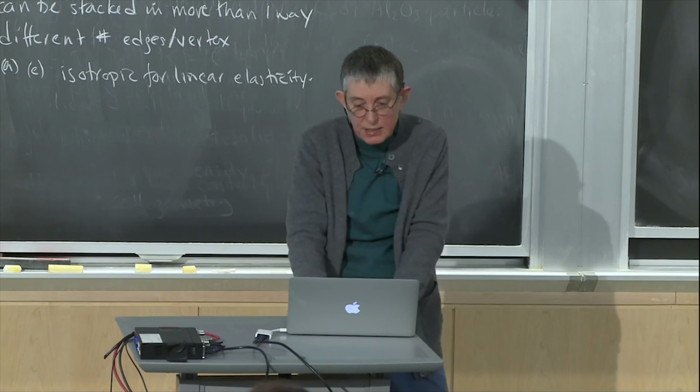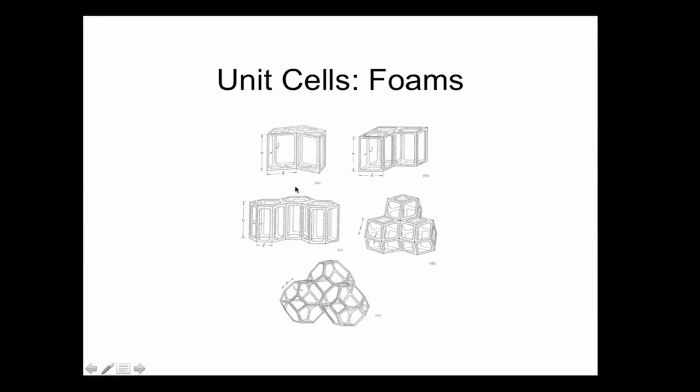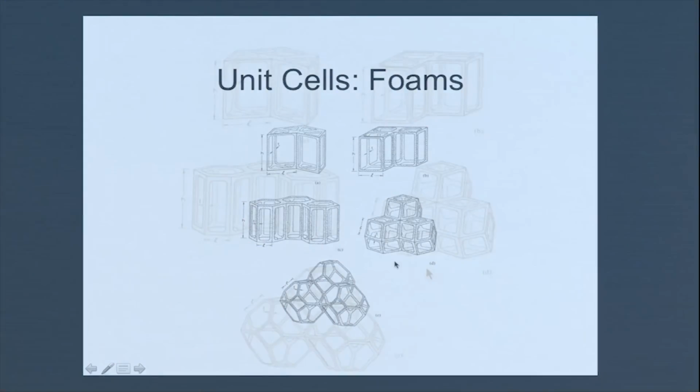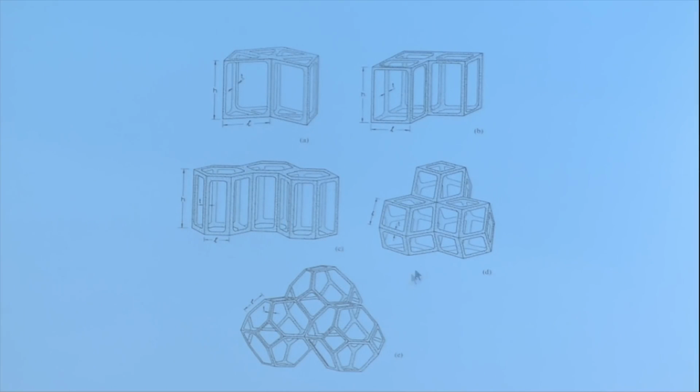And there's 3 cells here that are prismatic. We're not really going to talk about those beyond this. So they're not really physically realistic or interesting. But people use these 2 cells here in initial attempts to model foams. And this one here is called a rhombic dodecahedra. So rhombic because each of the faces has 4 sides, and dodecahedra because each polyhedra has 12 faces.